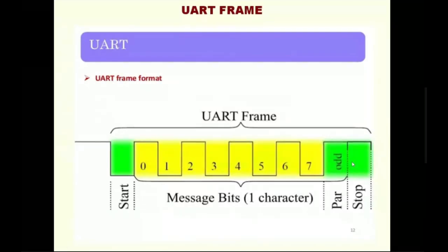How does a microcontroller identify that something is happening on the pin? This is very, very important. The microcontroller identifies that something is happening on the pin only through a transition on the pin. If there is no transition on the pin, none of the software algorithms, artificial intelligence algorithms, deep learning algorithms or machine learning algorithms can detect what is happening on the pin.